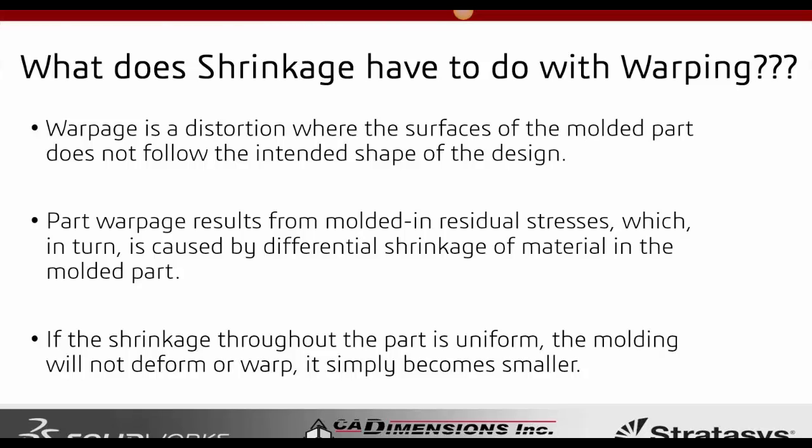You take your calipers, you measure what the shrinkage is and what the warping is, and then you rework your mold, and you do that over and over and over again until you have the right part. So whether it's 2 or 3 times or 5 times or 10 times, you would have to do it over and over again every single time until you have the right shape and size.